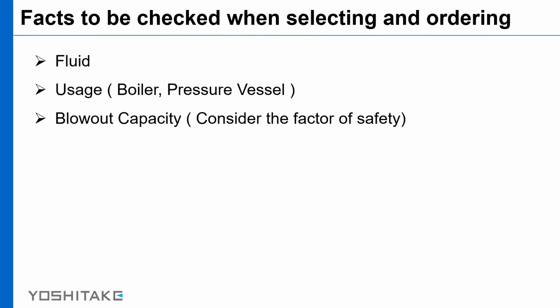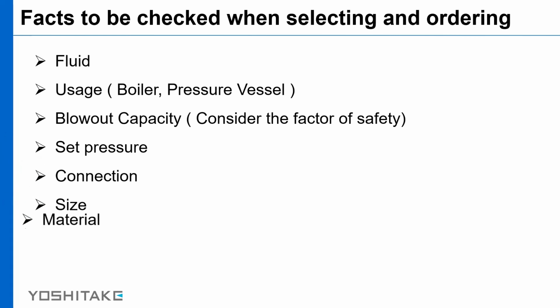And also you have to check the blowout capacity considering the factor of safety. And also you have to check the set pressure and also the connection, size, and material as well.